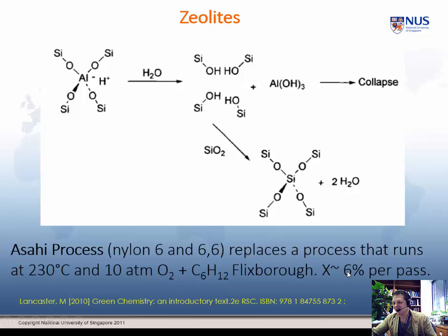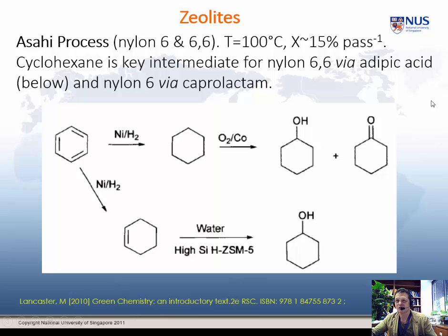But for this reaction, and incidentally only 6% per pass conversion, under these conditions and this high temperature, the reaction of water with this zeolite can result in the breakup of the zeolite into collapse, which of course is just what you don't need. You don't need your catalyst to decompose on you.